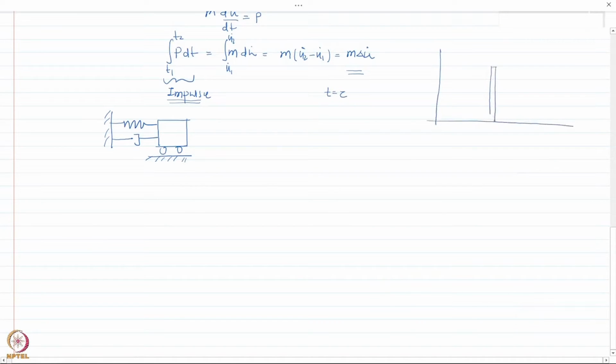Okay, this is at any time tau. The force p(t), the impulse, is at that time tau. This is a unit impulse, which basically means that p(tau) times d tau, which we have derived, is equal to 1 over the time duration.